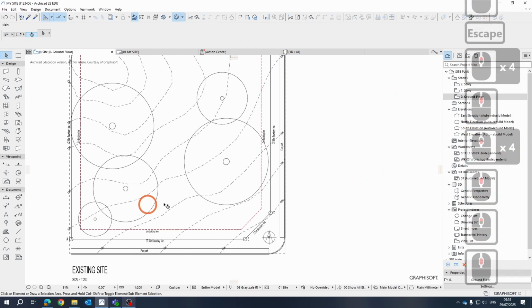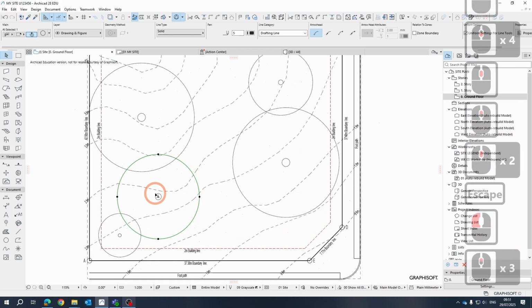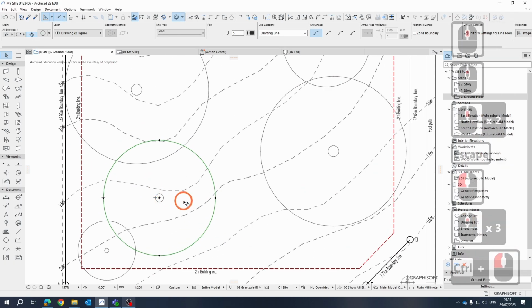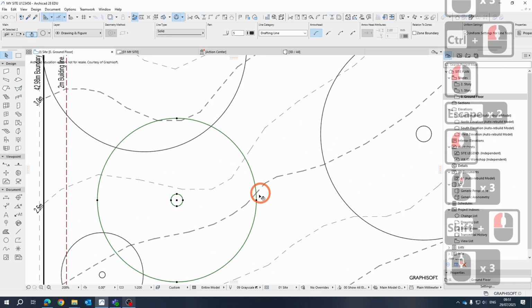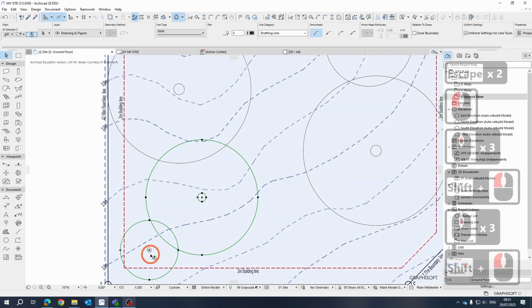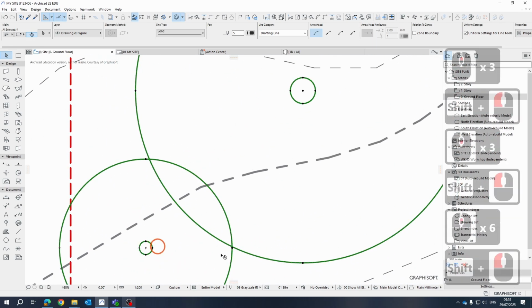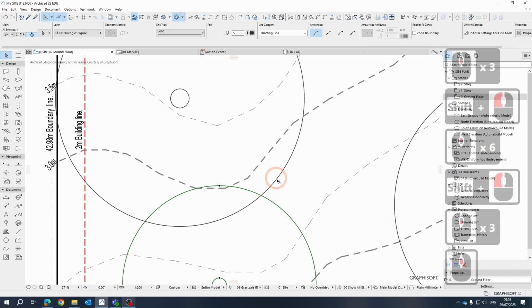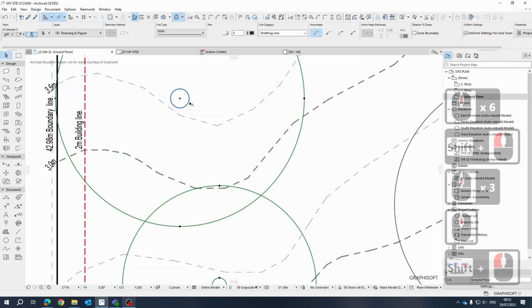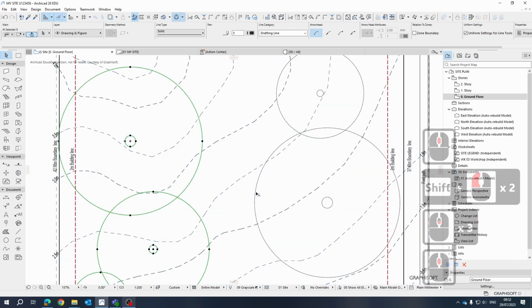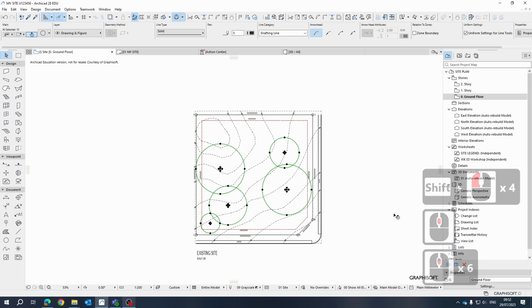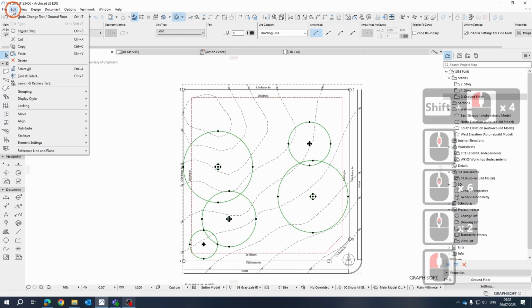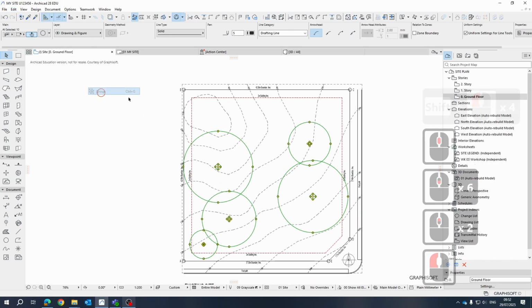We need to add some additional information. Now with the trees, these drawing figures, I'm going to make these a group and I'll delete them eventually. So I'm going to select all of them because I want to use a block for this. I'll explain why I want to use a block. So select that. Remember, holding shift down to select all these objects. Shift, shift, shift, shift. Okay, now that I've got all the trees, I'm going to make them a group. So edit groupings, so group them.